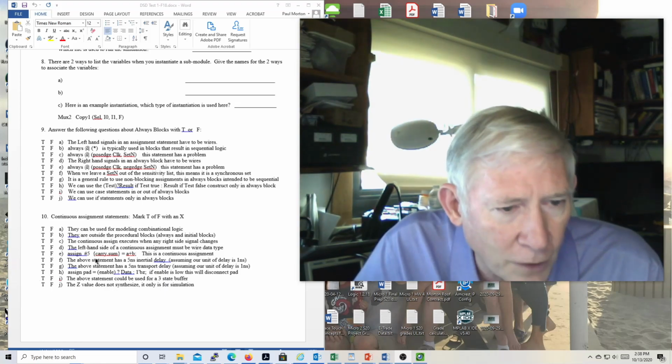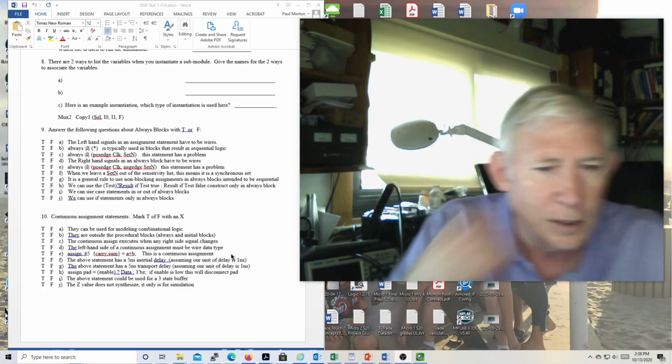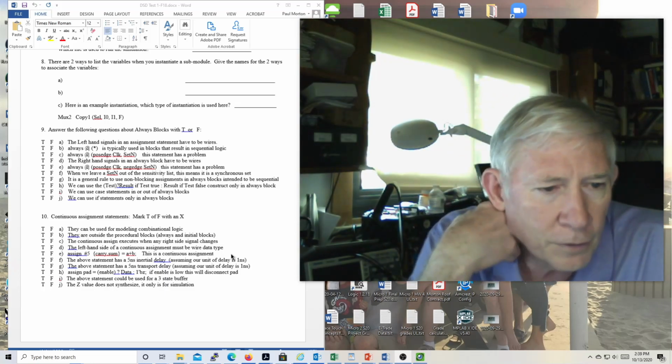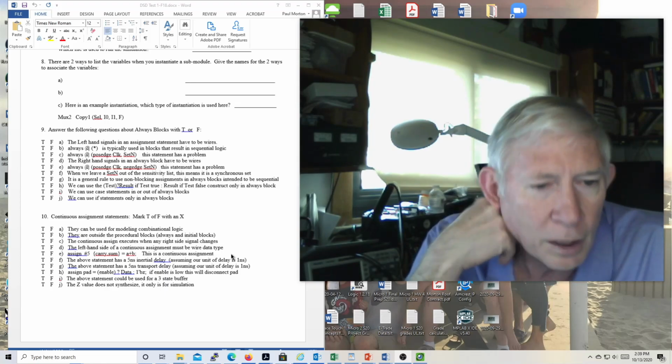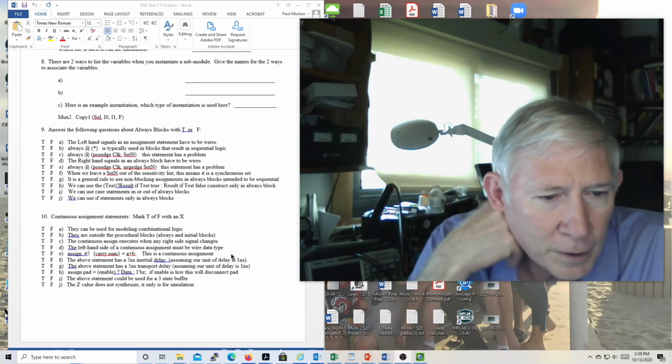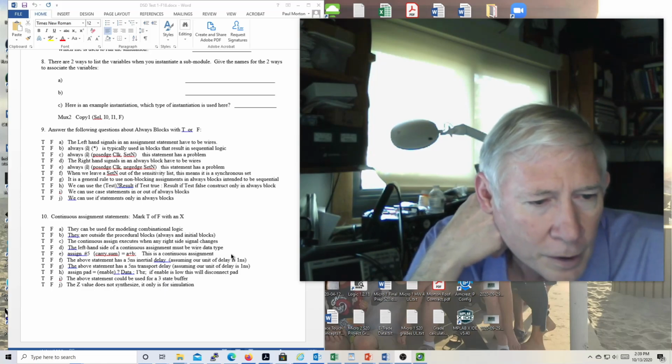Assign #5 carry sum equals a plus b. This is a continuous assignment. Yes, it is. The above statement has a 5 nanosecond inertial delay. Yes, it does. The above statement has a 5 nanosecond transport delay. No, it does not.